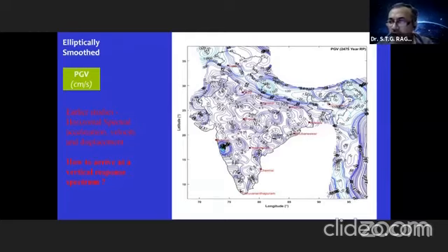So now in our codes, all our IS codes, most of you know that earthquake means only the horizontal things: spectral acceleration, velocity, and displacement. The vertical things generally are ignored and not used in design actually. The code says 2/3 of the horizontal one. So now I will show you some important things which we have arrived at recently about the vertical response spectra also.